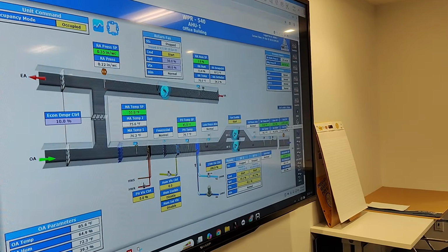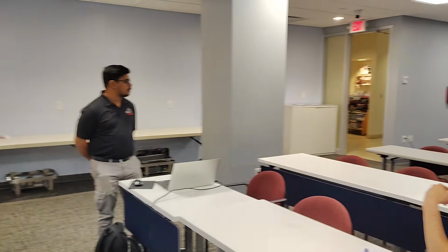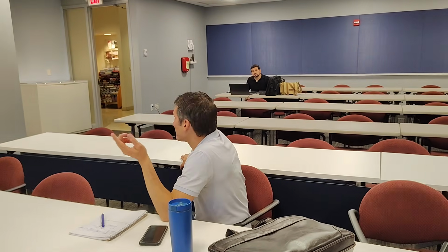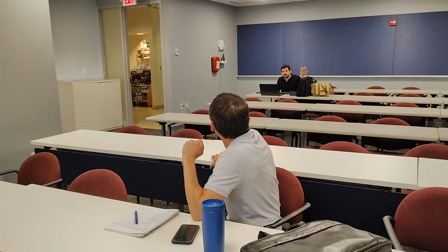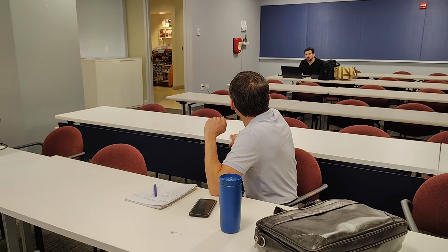duct, and we're still at not even 50% on the fan speed. No, it's 45%. We're not even at 50%. It's crazy. That fan speed should already be up to 90%. But it's not. When it does go to 50%, it's going at a very high rate. The RPM is like, I saw it today, 50% is going at 35 hertz. That's what it's supposed to be doing. But the RPM is like 1,000 or 800. It should be way more than that.